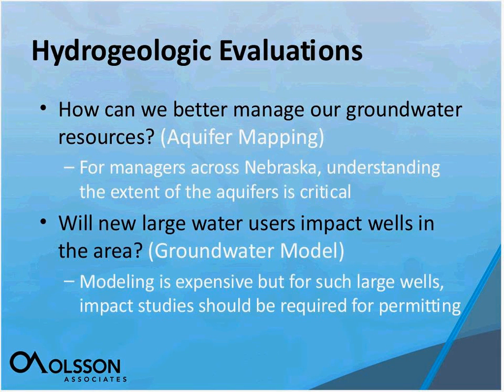The second question that we were asked by our clients was, will a new large water user impact wells in the area? Again, we used a groundwater modeling system. I want to mention that modeling is an expensive evaluation process, but for such large wells as we saw going in this area, and the high demand seen in this part of Nebraska in terms of irrigation, the impact study is critical to ensure that you're not permitting beyond the means of the aquifer itself.